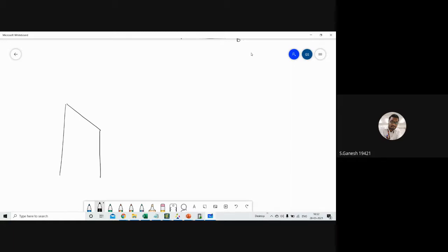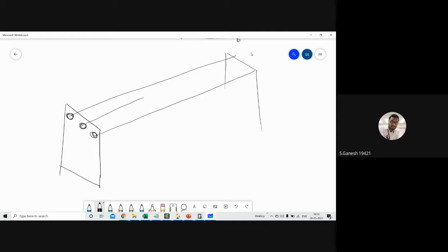When bar benders are making bar schedules, you see these bars. So 3 bars will be running throughout the section. This is an extra bar. So this will be bound here, so it will be looped here. The same way on the other side, up to a certain point. Where you see this cut portion, that is your change in reinforcement. This is called the cut element, where you make a bend in the bar.